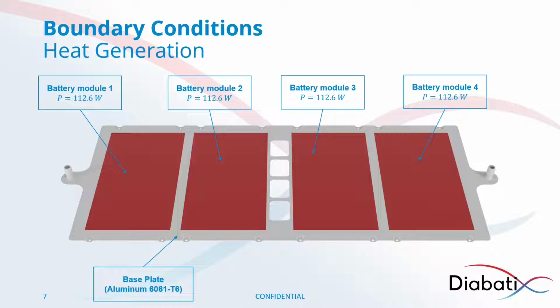What many people also do is that they draw a volume of their battery and simulate it as a volumetric heat source. That's also possible, but for today we will keep it with a heated wall. That's a little bit of what your preferences are.